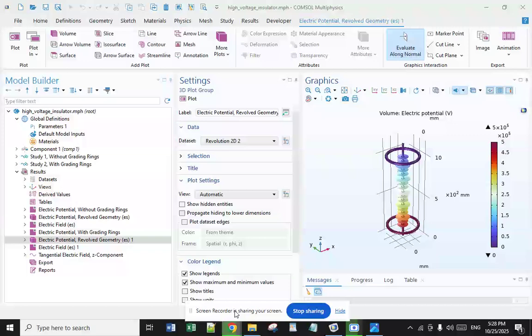And what are the main features and functions? Support insulators are typically made of porcelain, glass, or composite materials and are designed to withstand the vertical mechanical loads imposed by the conductors and electrical equipment they support. Unlike suspension insulators, support insulators are designed to withstand compressive loads and can have various shapes such as cylindrical, disc-shaped, or rectangular, depending on their specific applications.